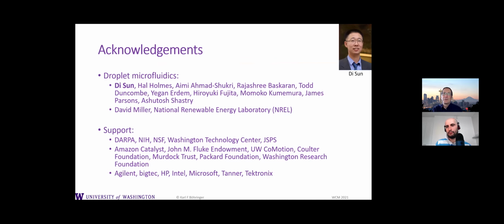Now, I showed two different ways to do that, either with vibration or with an electrowetting system. In both cases, there is energy input. For the vibration, you could actually work with a very high Q system that has a resonance frequency in that range. Many mechanical systems resonate at this 60 to 80 hertz. I don't have exact numbers right now, but you can show that the energy input would be very small, or could maybe even be helped by vibrations from wind or other environmental sources.